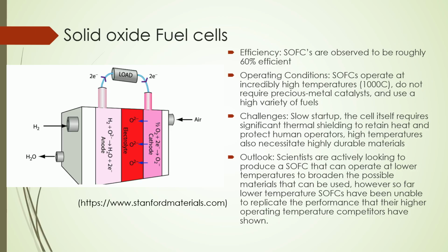The solid oxide fuel cell, which is one of the focuses of my project, is also one of the most commonly used fuel cells along with the proton exchange fuel cell. It operates via a hard, non-porous ceramic in the center as the electrolyte, surrounded by an anode and a cathode on either side. On the anode side, natural gas that has gone through a reforming process will enter the cell as steam, while on the cathode side, oxygen will enter.